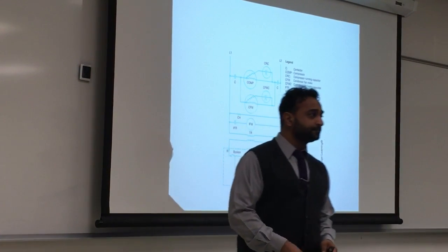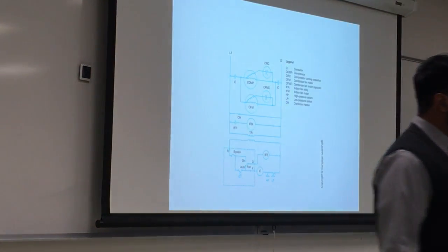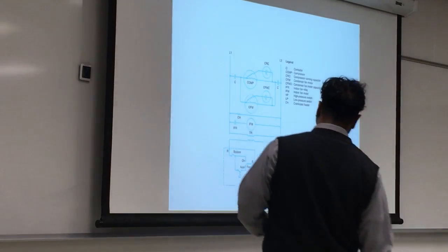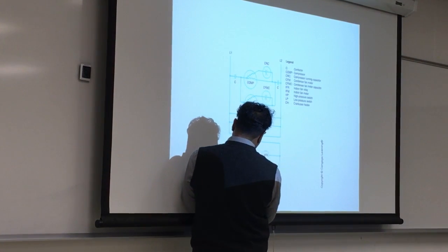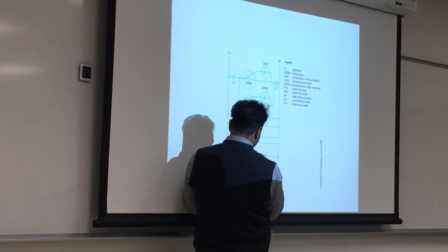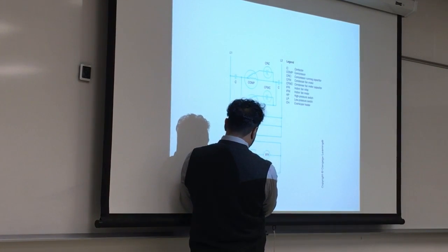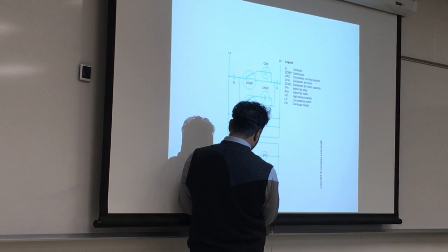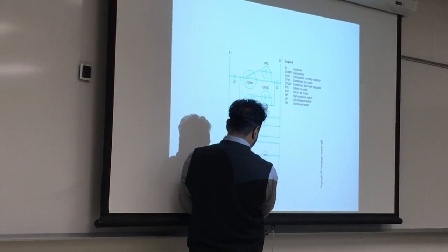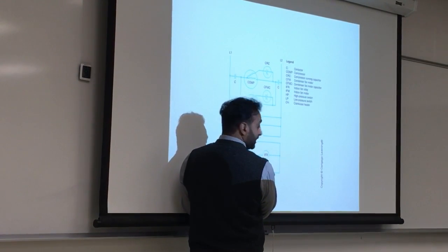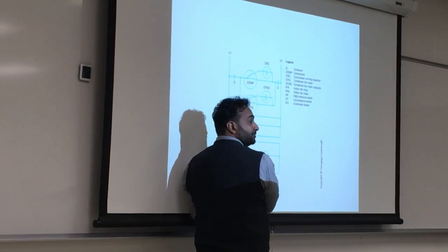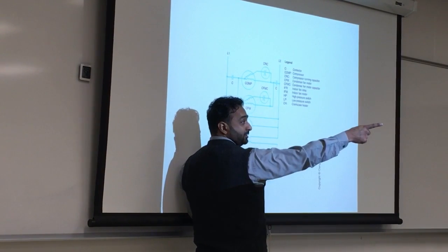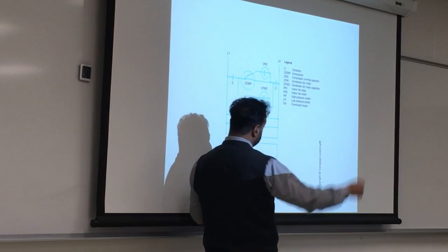Yep. So can you just repeat one more time the square part? I didn't get that. The square here, if you notice, has three wires which connect to the system. This one will switch between the fan on or automatic, and this one is the thermostat, which will close the circuit if it's too hot. So the whole thing here is the thermostat, which is over there and controls what's going on.